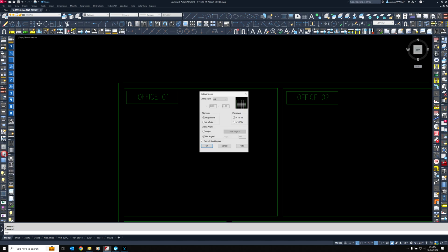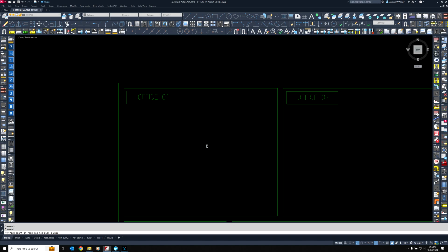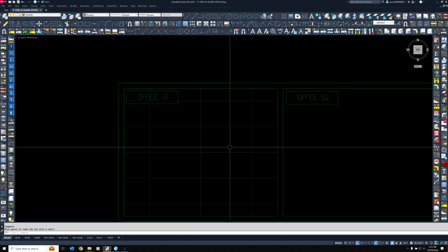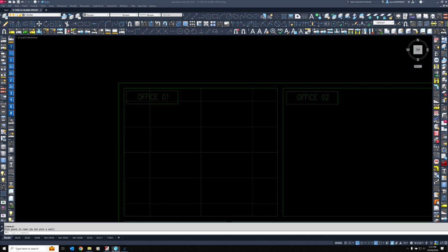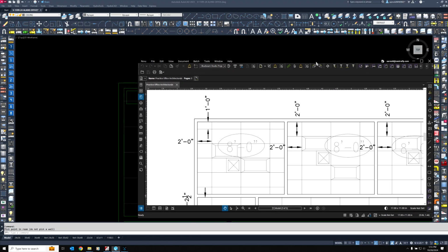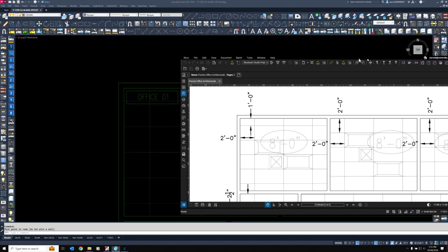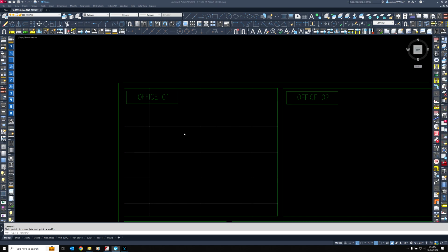We come down to your left and you should see the S and the ceiling grid hatch. So we're going to set up the ceiling 4x2. These could be anything depending on the project, but in this case, let's hit OK, insert. All right, the ceiling grid is in, and it matches this 1 foot down, 2 foot to the right. We don't have to move anything.